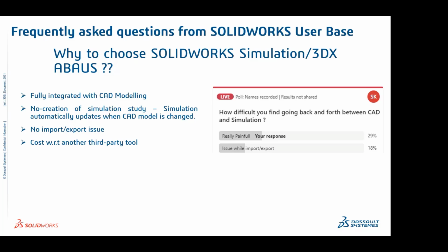And one more thing is, with SolidWorks and 3DEXPERIENCE, whatever parameters you use in the sketch can be used for driving your optimization. The simulation tool itself will tell what value of thickness, or what material you have to use, with respect to the optimization. And in the case of engineers and analysts, one more key thing they usually tell is, we have an issue with input.